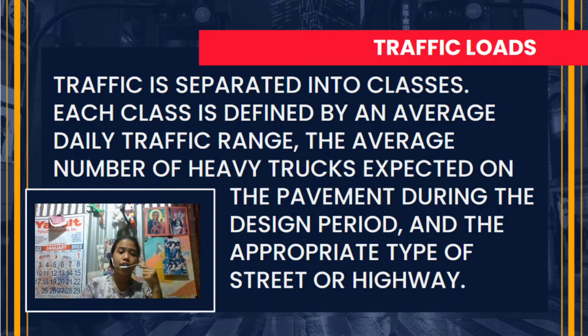period. Residential streets, rural farm roads, parking lots of less than 500 stalls, airports, 7,500 pounds maximum gross weight. Third class is medium, up to 700 autos per day, 70,000 to 150,000 trucks expected during design period. Urban minor collector streets, rural minor collector streets, parking lots of more than 500 stalls, airports, 15,000 pounds maximum gross weight.